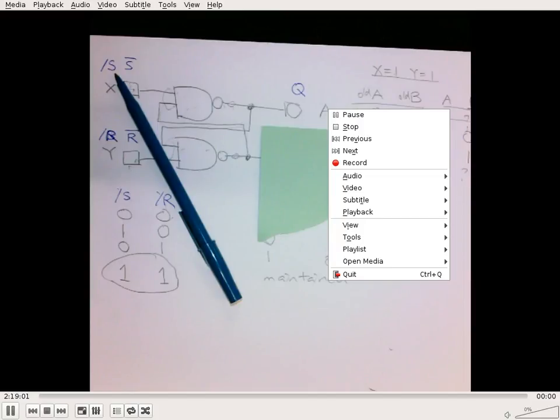It has to do with can I use multiple mechanisms to trigger the active signal. And anything that is active low is easy to deal with. This is completely out of the scope of this class, but I think it is kind of useful to know why that is the case. With the active low signal, normally they have what we call a pull-up resistor. This is a positive voltage, I just call it VCC. In older computers, VCC is 5 volts, but they are really low these days. It depends on what type of logic system you use.